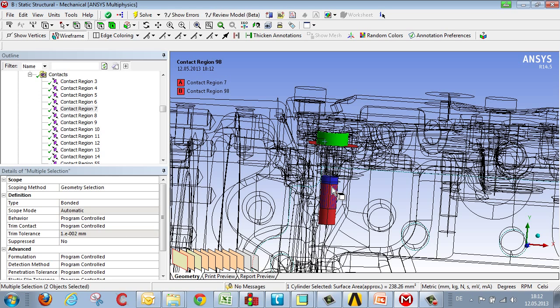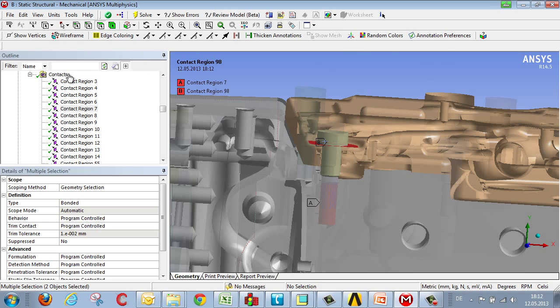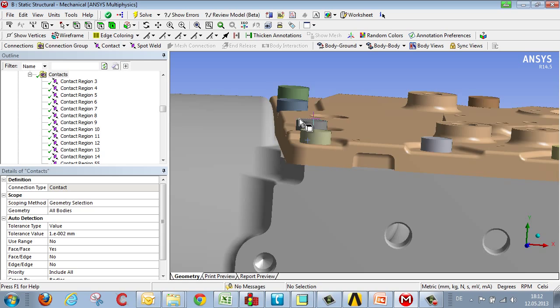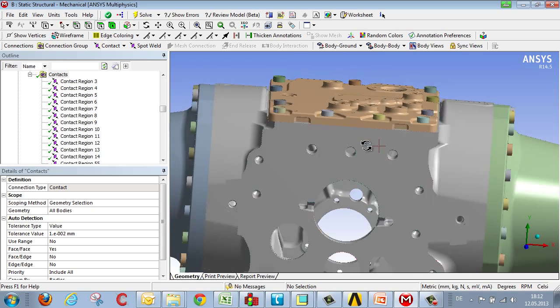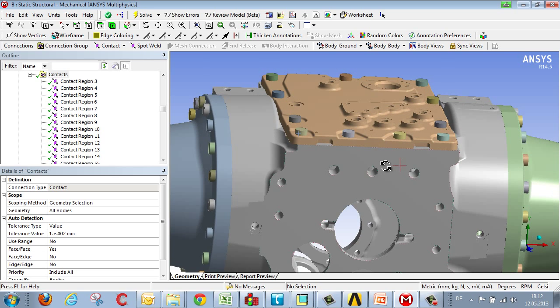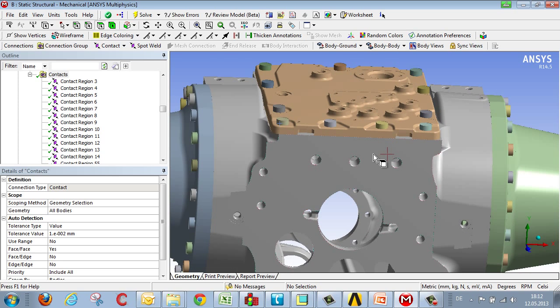So it's a very efficient method that has to be tackled using the correct tolerances. However, this method enables me to go a lot further in just one step than generating all the contacts manually. So when loading geometry, it always makes sense to be aware of how big the gaps that need bridging are, and to work with this contact detection tolerance, and also to put some effort into finding the correct settings, because overall it really speeds the process up.